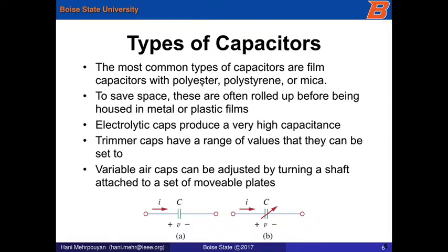Now, the most common type of capacitor is the film capacitor. These are very common to see, and I will probably show a picture of one in class, but they are rolled up, they look like a cylinder, and basically there's either mica, polyester, or some other form of dielectric between them.